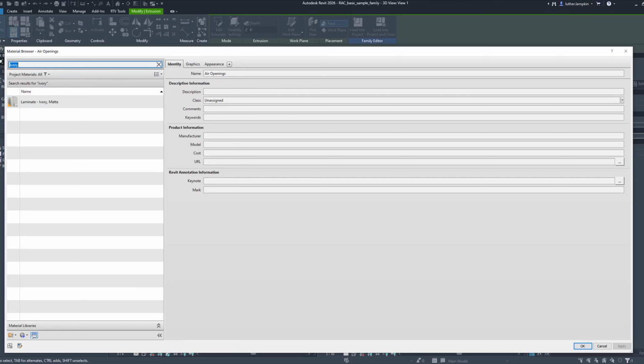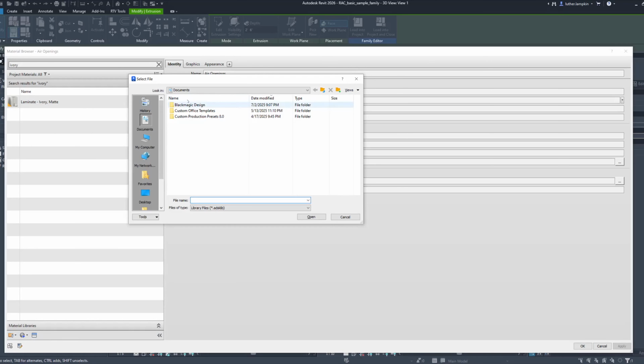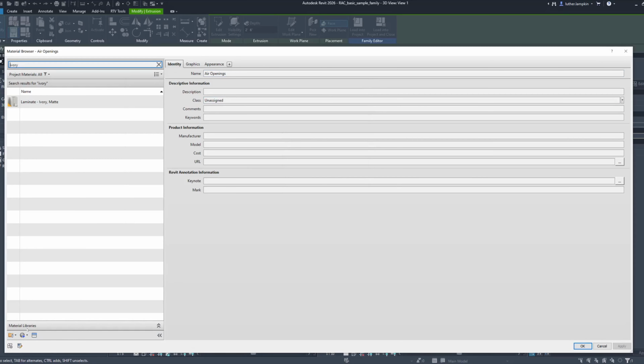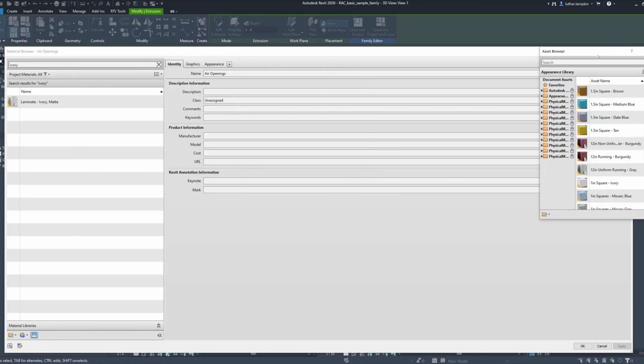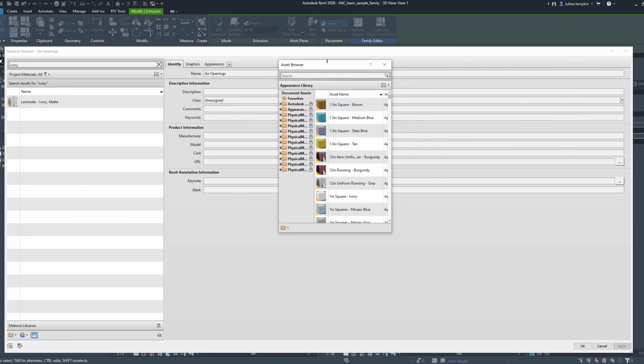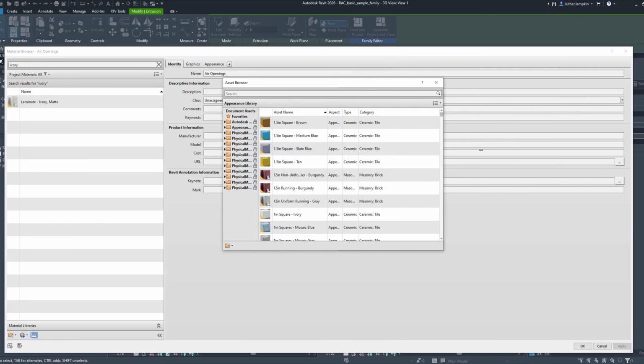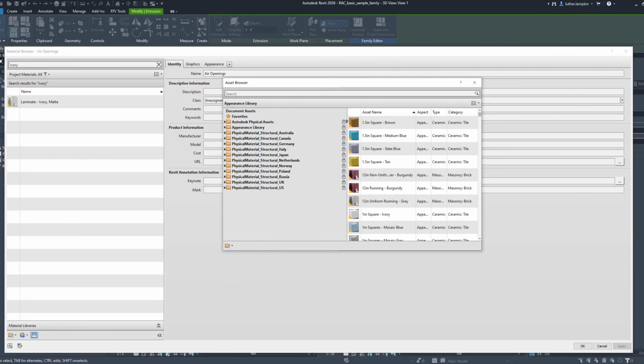And if you need to go out to the material library and add anything else or a new material, or find where this is, it says open existing library, and then you can see all the different information that's here. All right, and here, asset browser. Here's all the physical materials that Revit uses. Okay, you can go back over here, look at that, and go to different ones. We'll call them Autodesk physical assets. That's the one I like to use a lot.